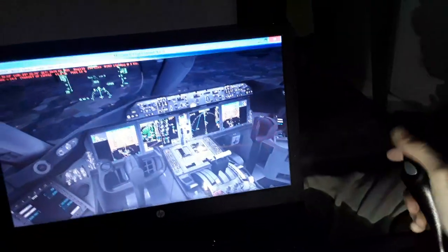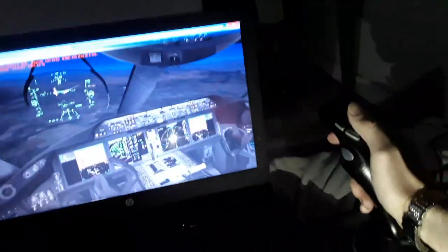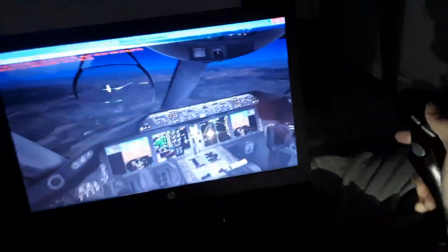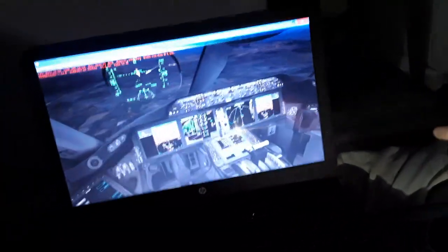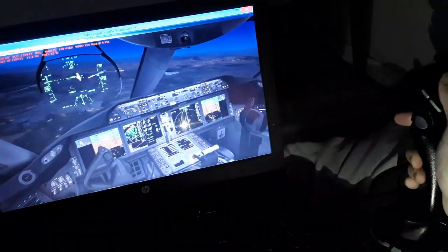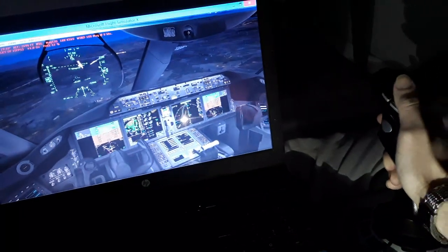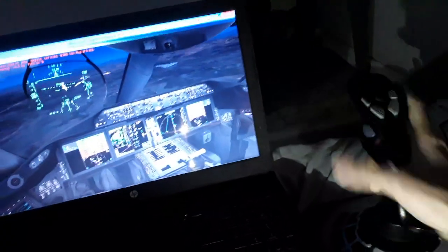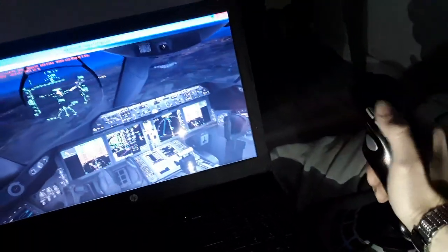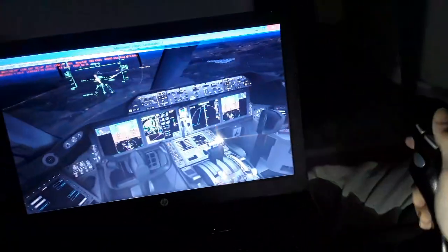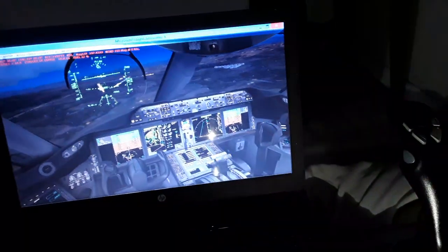So a little bit more thrust. We have full flaps, landing gear extended, keep the airspeed, and we have some side wind. We need all the flight controls when we have side wind to combat the side wind and align with the runway heading, like the rudder pedals and the ailerons and the spoilers. This is our side wind approach. We have also some gust wind, and this makes the approach more difficult.